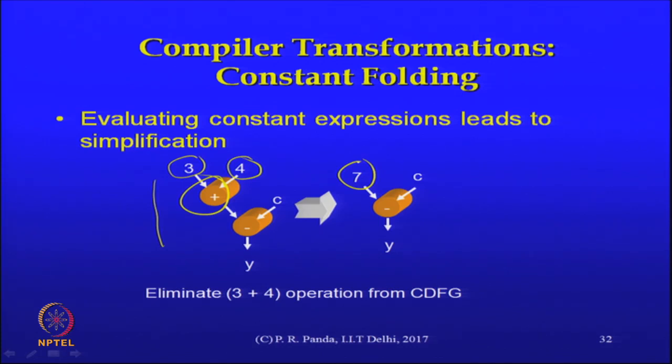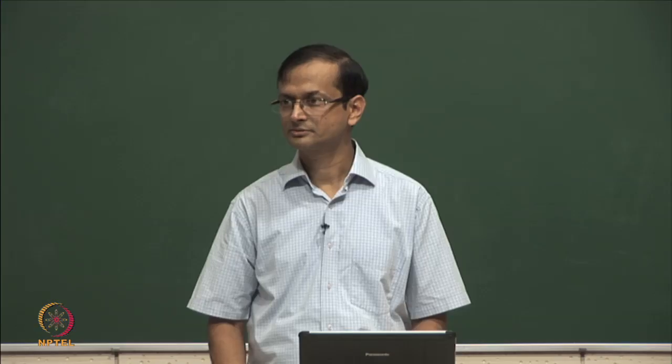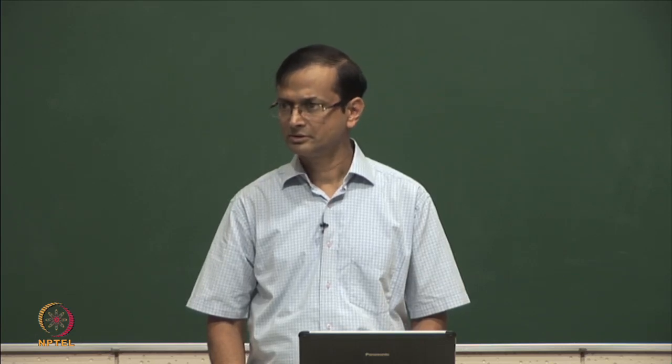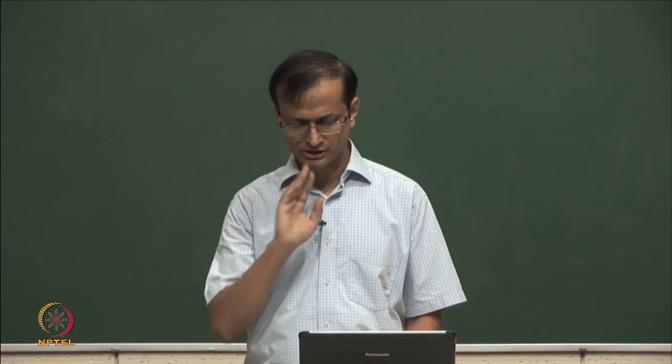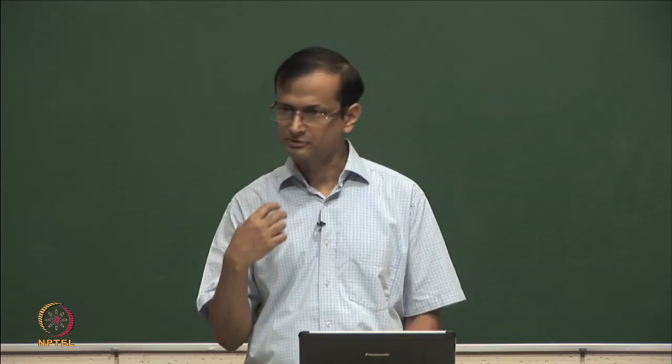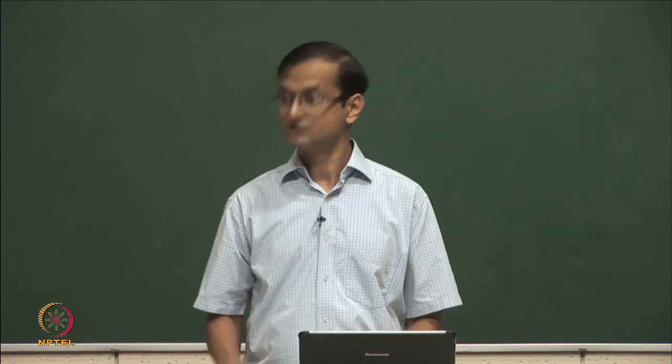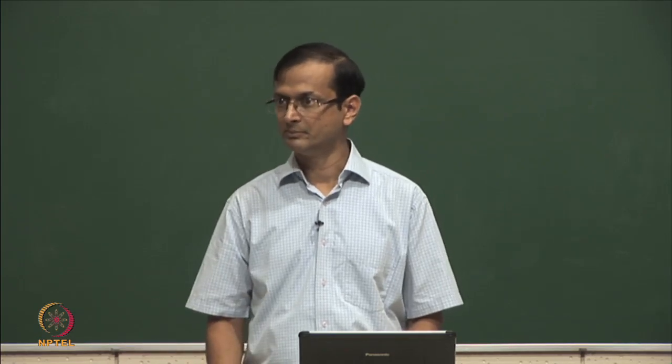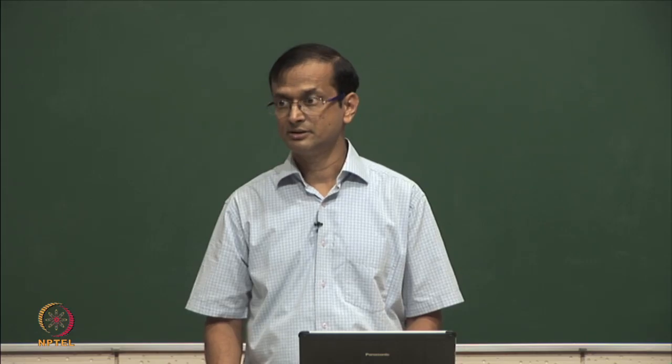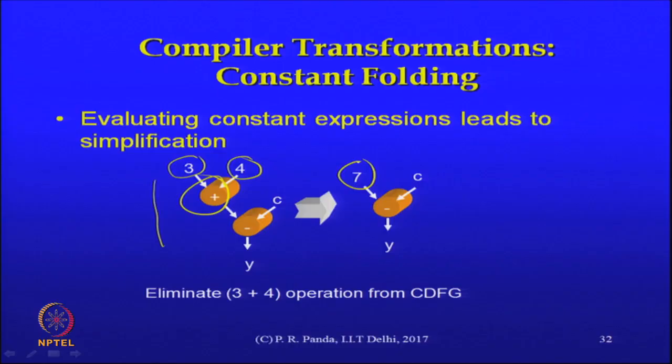For that argument, that we don't want to load the initial step and we want to see if it is working correctly, compiling first, we can provide optimization options. For example, in typical GCC you have optimization options with one or two levels. Similarly in such a front end. Even to a synthesis tool, you can provide levels of optimization like you would to a compiler. That does not affect parsing. That affects what subset of the available optimizations would be performed, but we still do not do it during parsing.